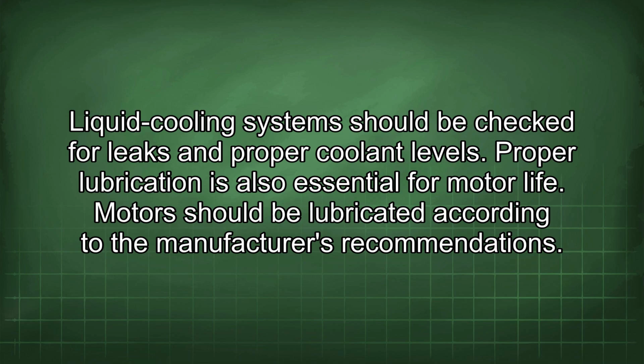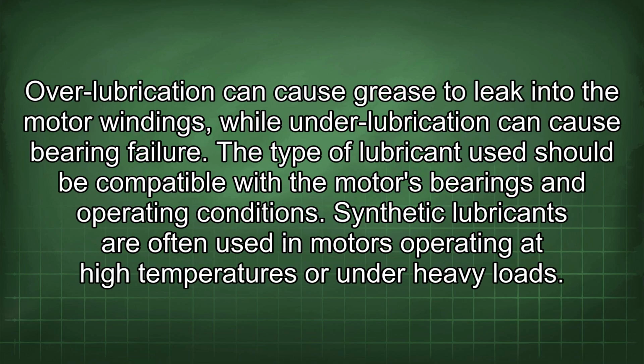Proper lubrication is also essential for motor life. Motors should be lubricated according to the manufacturer's recommendations. Over-lubrication can cause grease to leak into the motor windings, while under-lubrication can cause bearing failure. The type of lubricant used should be compatible with the motor's bearings and operating conditions. Synthetic lubricants are often used in motors operating at high temperatures or under heavy loads.